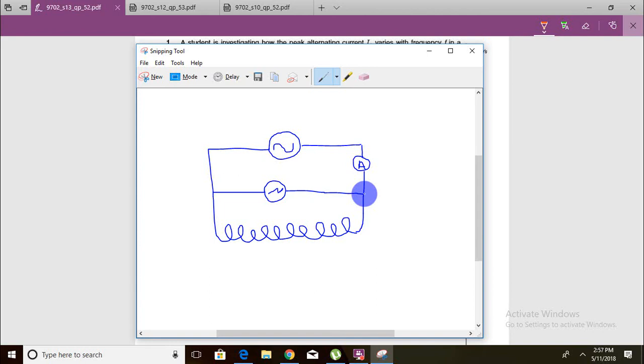The vertical displacement is basically going to be the voltage, and the horizontal displacement is going to be the time. And from the time base settings and the Y input settings, you can figure out what one block stands for. Maybe one block means 1 millisecond horizontally and 0.1 volts vertically, and from that you can figure out the value of the peak voltage. Actually, you already know from the signal generator, because that was the setting you put in, but you aren't sure how accurate the signal generator is, and if you're actually getting a waveform with that particular V out and that particular frequency, and from the oscilloscope you can be sure. And you can also monitor that it remains constant and does not change during any instant of the experiment. So that is the purpose of the oscilloscope.